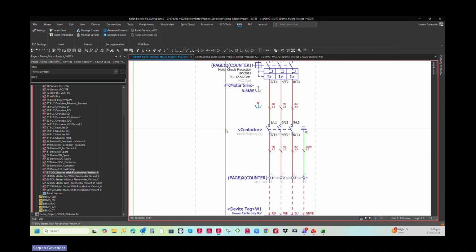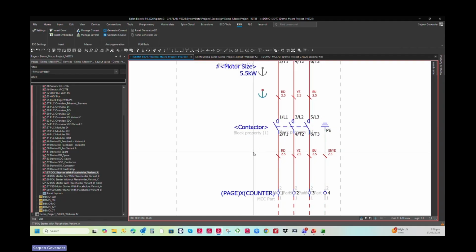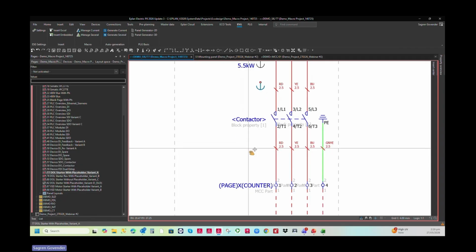So in here, you can see I've got a few different types of brackets. I've got a sharp bracket. So basically, I'm writing this contactor DT. So when I get to my Excel sheet, I'm going to write whatever that DT is, whatever the page, just say 40K1. It'll automatically write 40K1. And the next one might be 40K2 or 40K3 and so forth.